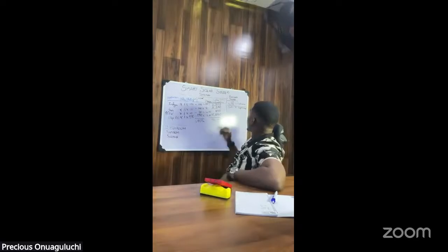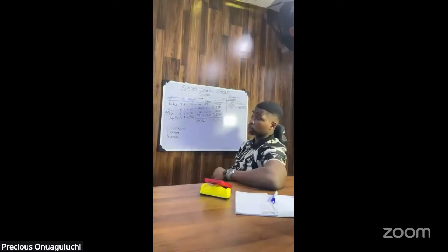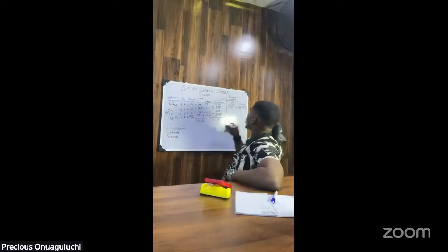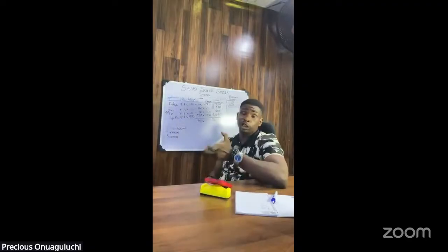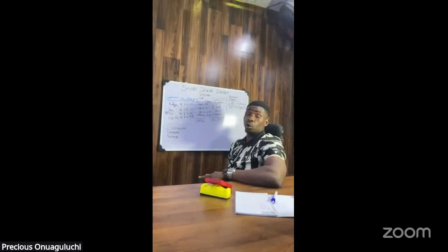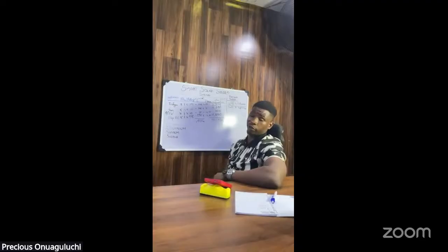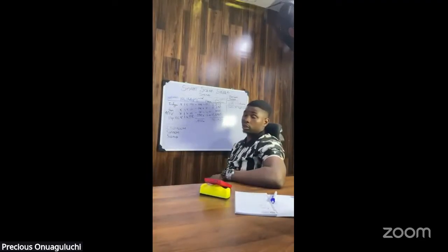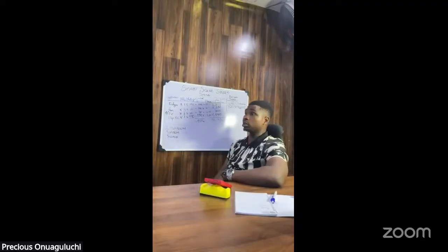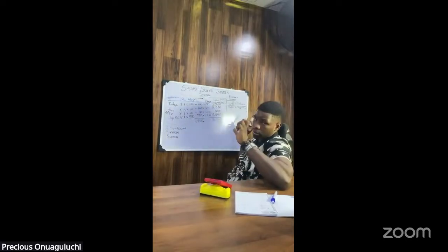So now I've written something that I've not mentioned, system inefficiencies. So we can always just make an assumption. Remember, no system is perfect, right? There's always a loss of energy. You understand? In cabling, in inverters, in your batteries, no system is perfect. So you can always assume a figure, maybe 90% efficiency or 95% efficiency in your system. So this is the formula, right?